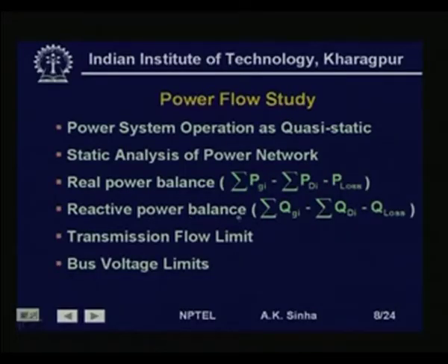Similarly, the reactive power balance equation also holds good, that is, total reactive power generated by the generators or the transmission lines must be absorbed by the loads and the losses in the series element of the transmission lines. So, both real and reactive power balance equations hold good.